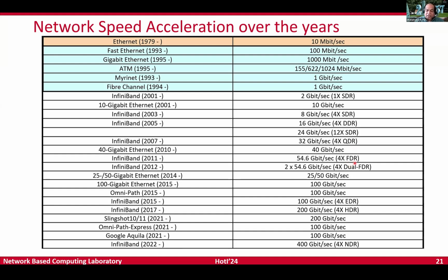Okay, so that's how this FDR is introduced. And interestingly, by that time the encoding technology also improved. Here they were using 8b/10b encoding, but then the encoding community came up with better solutions which can do 64b/66b bits. It's a kind of encoding where it's only with a very little overhead that you should be able to do this encoding.